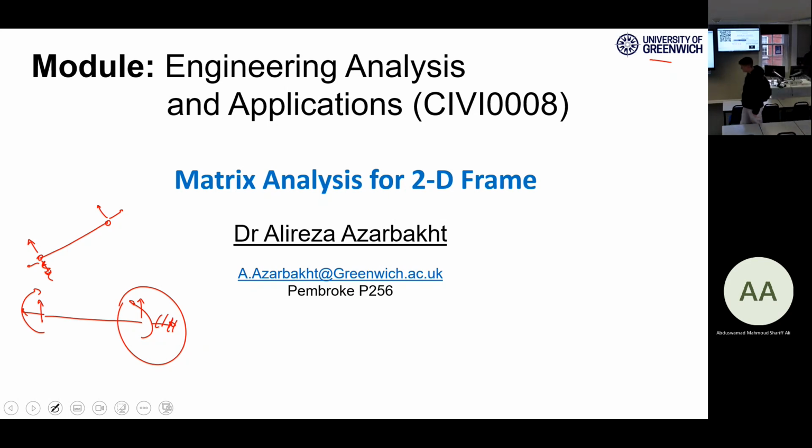However, in the frame structures, frame means it can be a combination of beam, column, etc. Right? This is a frame structure. It's a building. When you model your building with a fixed frame structure, so if you are working with your concrete or steel project, well, here you were doing something like this with ETABS, etc. When you model it in ETABS or by hand, whatever, the number of nodes you have, you can count them and multiply by what to get the degrees of freedom. So what do you think?